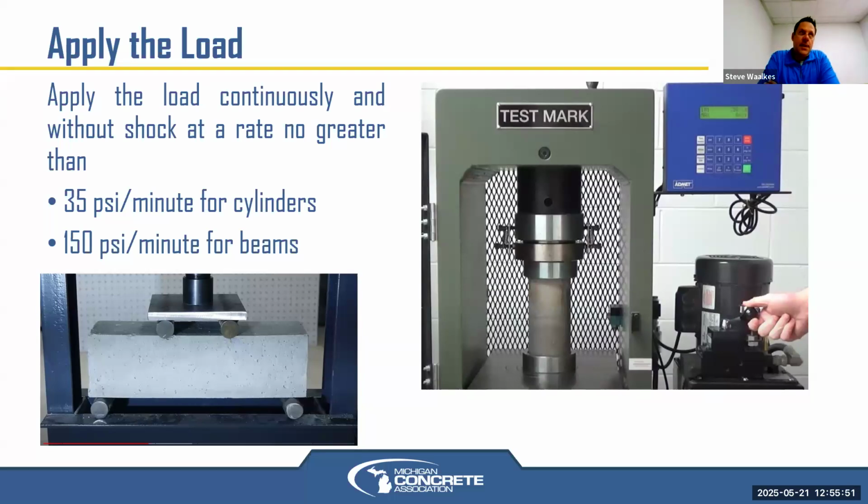It's very dependent on the finishing techniques. We typically see it used where there's been a strength concern on some flat work or on a floor, and it's usually because of some other reason why the cylinders or whatever broke low, and then we go to the in-place slab and we say, yeah, but it's rebounding to a 5, and that's analogous to a 4,000 psi or whatever. However, it's very susceptible to the finishing operation of the surface.